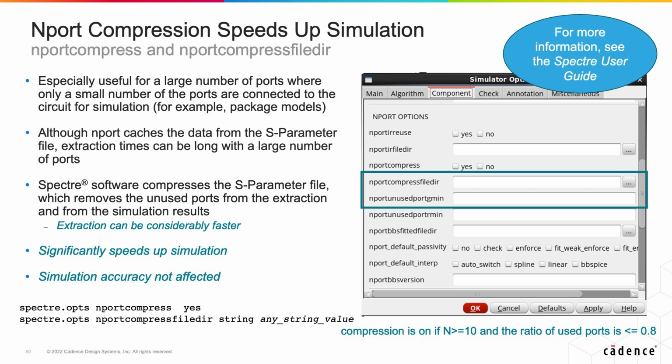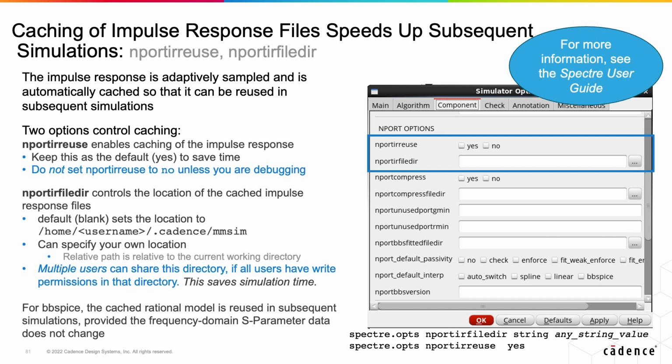And then endport compression. In order to speed up simulation without actually affecting accuracy, we would like people to use this endport compression. This is where the buttons are. If you want more details on why you are doing any of these things, go to that article on 7 habits of highly successful S parameters, because this is just a few slides from that 90-minute presentation.